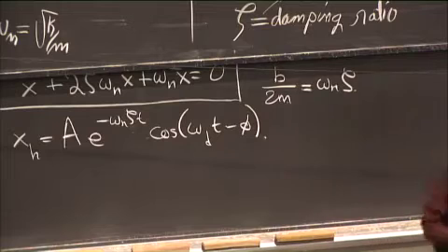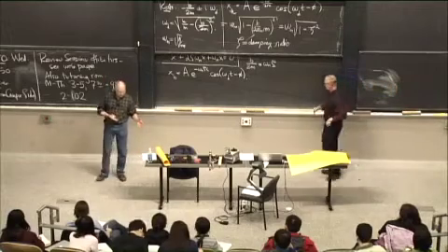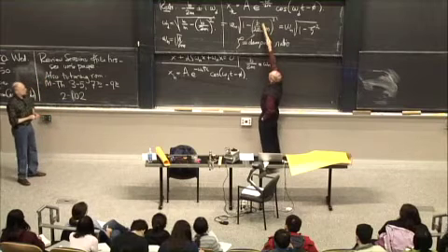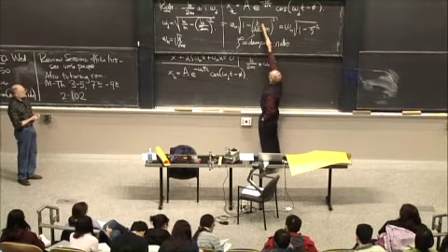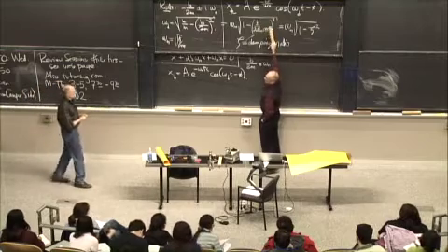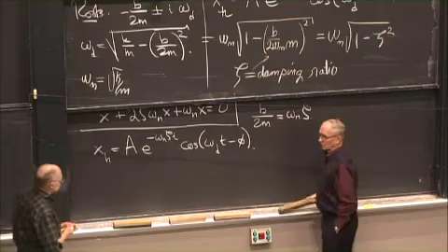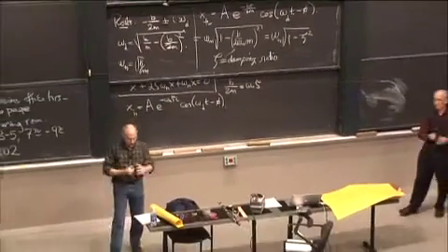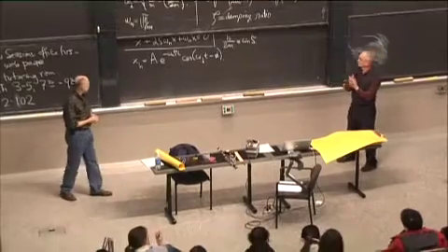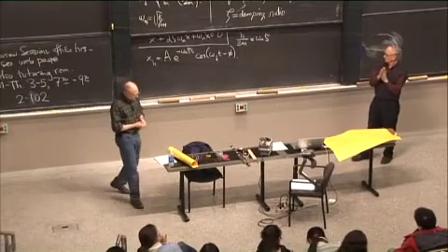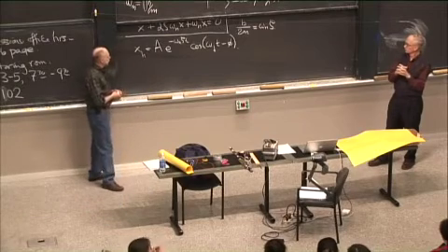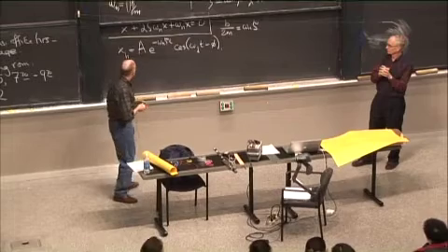So you mean if I switched units from feet and seconds to meters and hours, the zeta wouldn't change? Omega n would certainly change, but zeta wouldn't change? Right. As long as you're consistent up here, newtons per meter per second and kilograms, that'll work out. Or you can do it in English units. So this is this amazing thing. It's a ratio. It doesn't depend upon units at all. It's an invariant of the system that you're looking at, and it tells you whether it's overdamped or underdamped. So maybe we can actually measure these things in a real system. Shall we? Let's see.